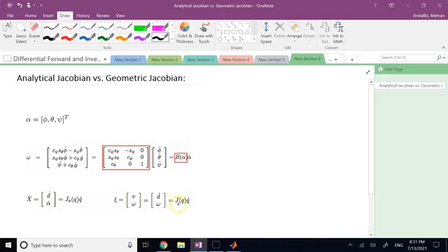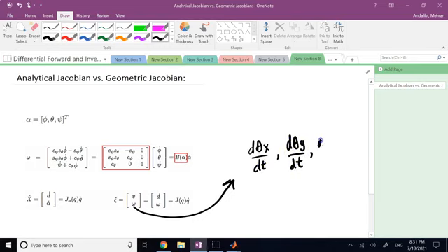When we define this geometric Jacobian, this J that we calculated so far, the components of this omega were what? The time derivatives of theta x, theta y, and theta z. Where they were the absolute angles of the end-effector frame in the base frame.